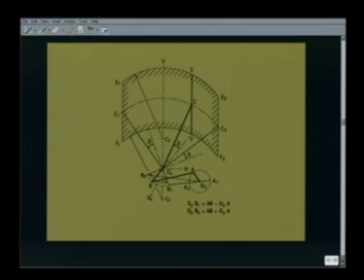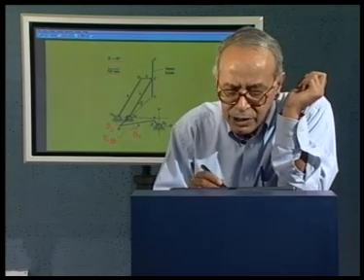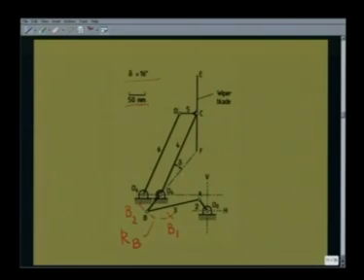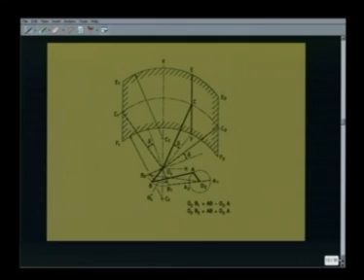Now, as we know, because the second part of the mechanism was a parallelogram, this line CD always remains horizontal and the wiper blades always remain vertical, because there is no rotation of the coupler of this parallelogram linkage. We have already determined the extreme positions C1 and C2, so I can draw the wiper blades as E2, F2, and the other extreme position when C is at C1 as E1, F1. So, these are the two extreme positions E2, F2 and E1, F1 for the wiper blade.